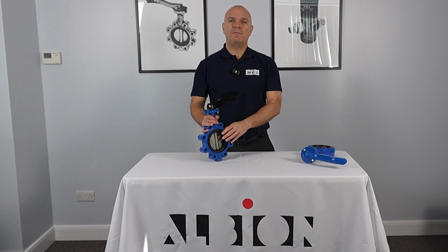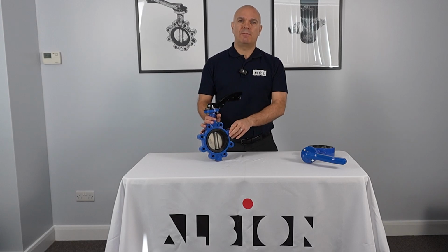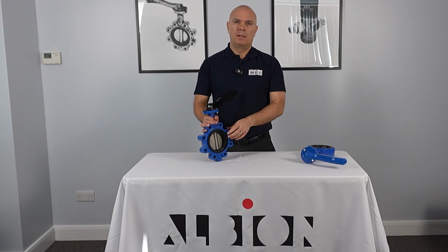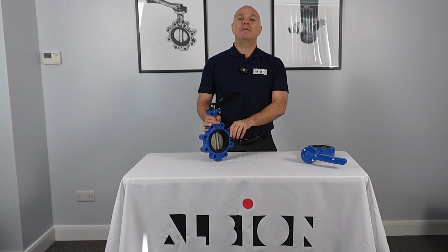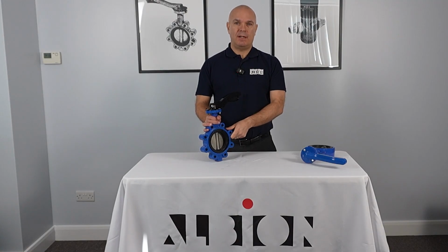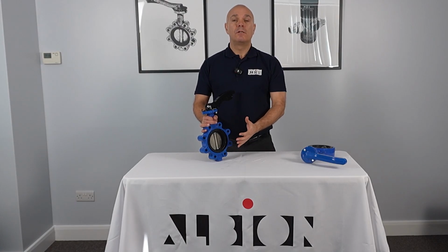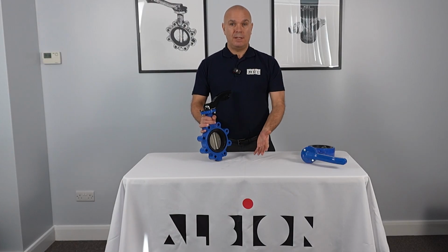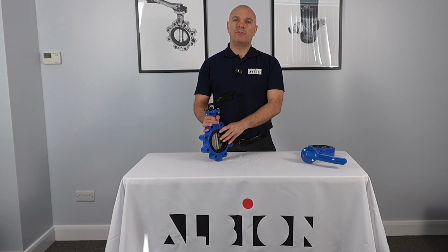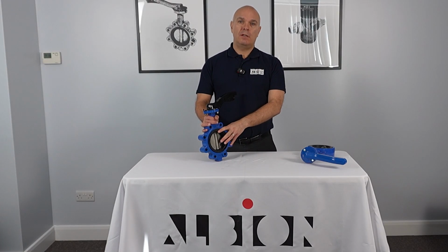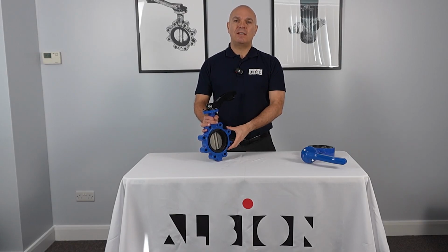Now let's talk about specific standards that Albion's range of butterfly valves are manufactured to. Albion's range of butterfly valves are manufactured to BS EN 593. This standard links directly to several other relevant standards. All of these standards, when used in harmony, define specifics such as general design, working pressures, temperature limitations, material of manufacture, geometric requirements and their tolerances, and any specific testing that is relevant to butterfly valves.